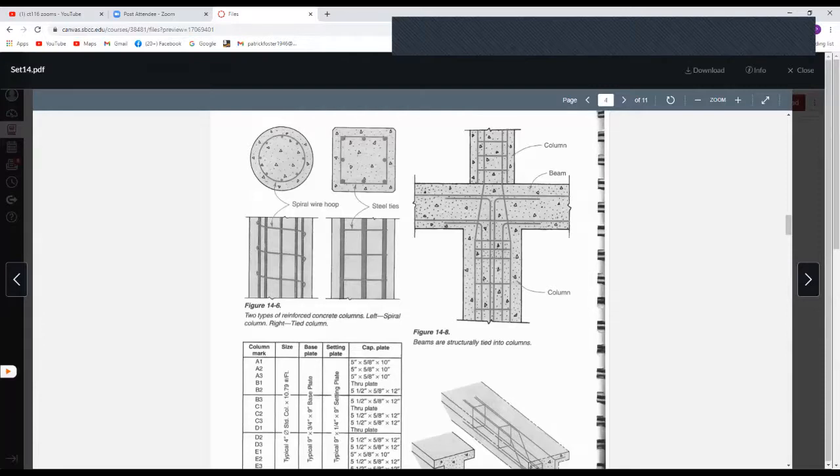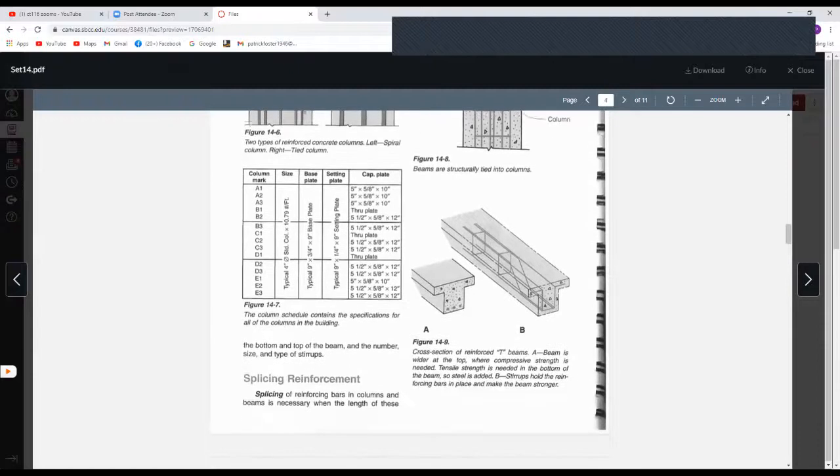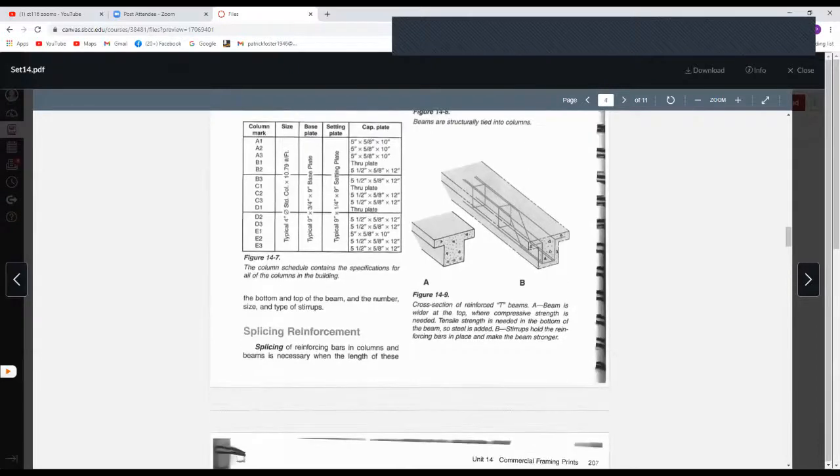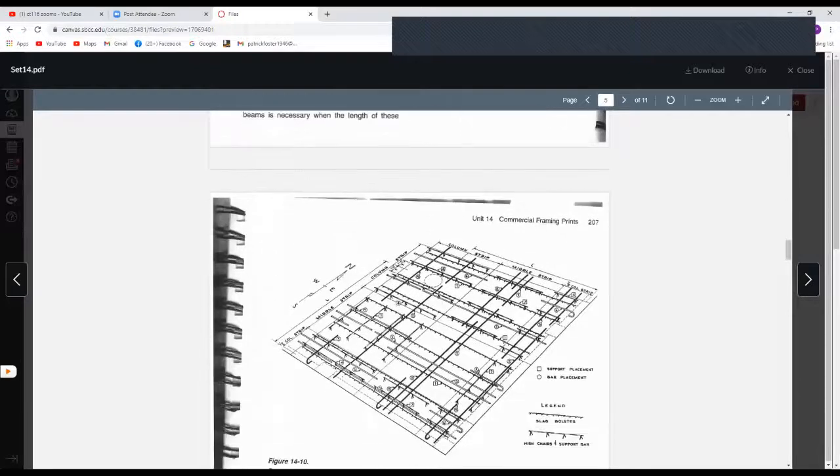And then the beams, sometimes they integrate the beams with the columns and they just pour it together, and there's all this rebar in it. So it's what's called an integral pour. This looks like it was poured and the rebar stuck up, and then they poured another column for the next floor on top of that. Let's see. These are just shapes of types of concrete.